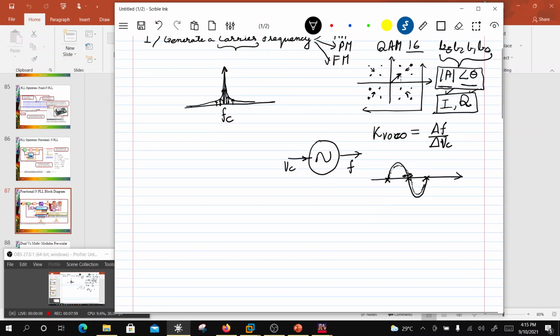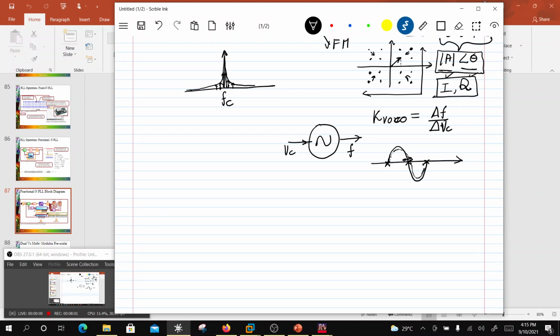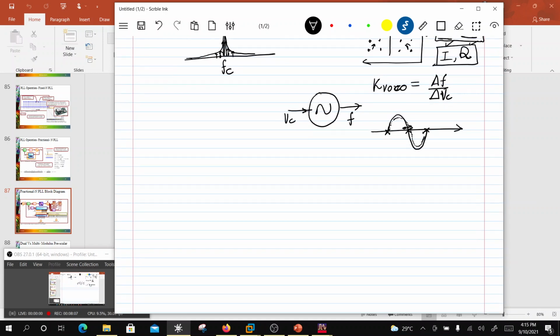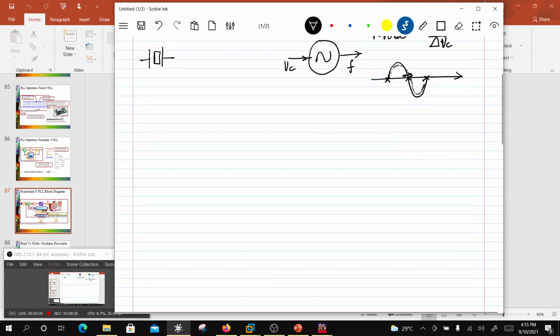And this phase noise is nothing but noise which is up converted from the devices, right? And then there is a Leeson model which I have discussed in another series, so I'm not going to discuss that over here. Maybe later on I would cover that. So we want to stabilize the VCO with respect to a reference, and that reference is a crystal, and a crystal is going to give you a very good phase noise.